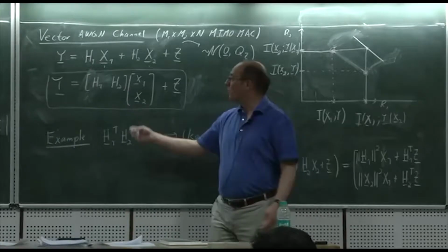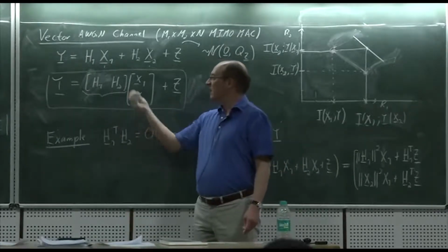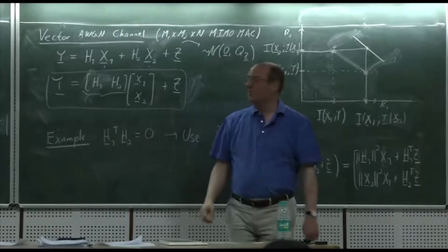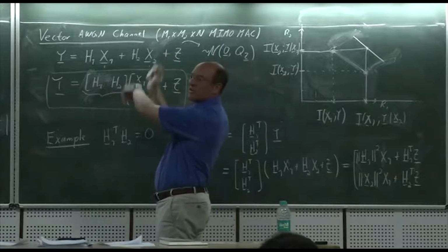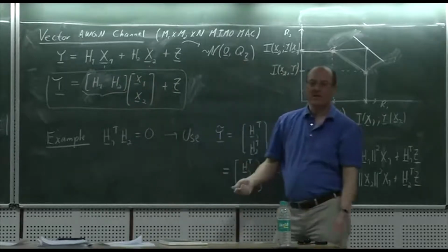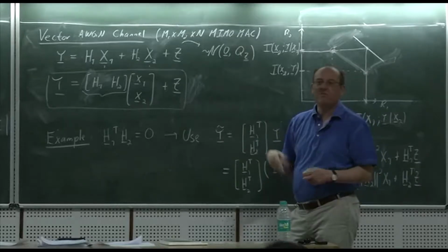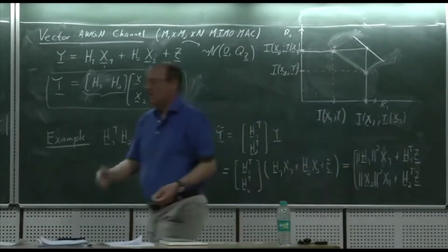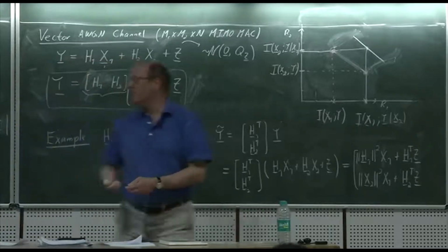And that'll work well as long as this matrix here has, of course, full rank, but also is well conditioned. So if this here becomes a fading channel, sometimes you might get a really lousy channel, but as long as most of the time it's good, that gives you actually pretty good rates, and that's the most common way of doing multi-antenna communications. And generally it works quite well. But there might be some cases where that doesn't work well, of course.